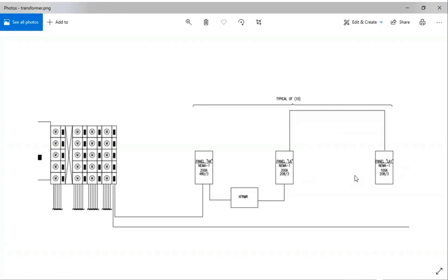In particular, could he do it with recurring panels? You can, with a little bit of work on your part. We don't have any way to model this directly, because our recurring panels really assume a single panel, not a recurring group of panels. So you can't define 3 panels in a recurring transformer and have those recur as a group. So instead, what I recommended was that he model this whole thing once as a typical, using standard panels and transformers.